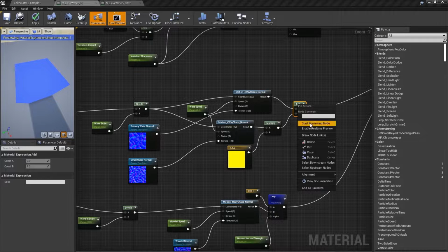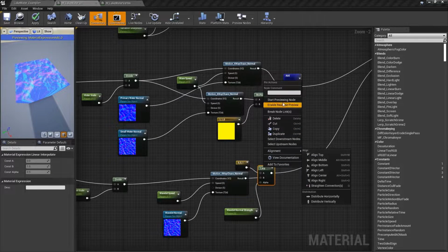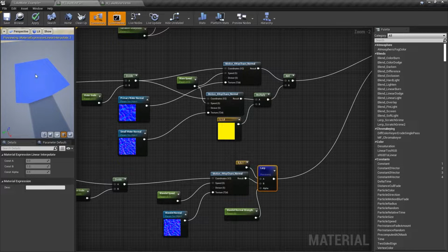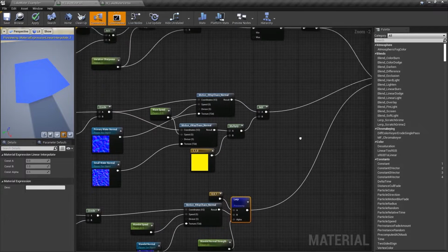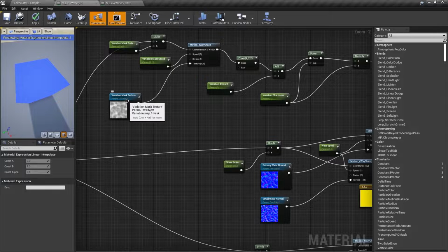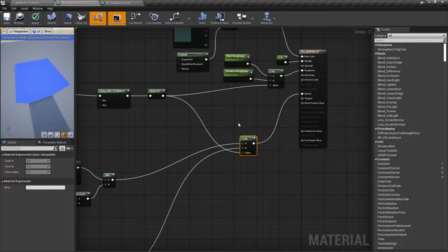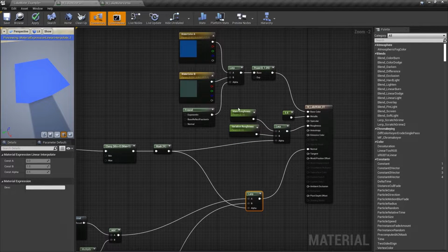One on the top, which is our rippling motion we can see here, and one on the bottom, which is our more solid and no motion. And by lerping each pixel based on how much this mask texture is taken from black to white, or nothing or something, it lerps it into what we can see. It also uses that same information to lerp how rough it is, based on how much of a pixel is being shown, whether it is more of the flat surface or more of the rippling surface.